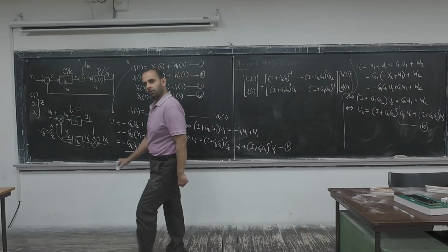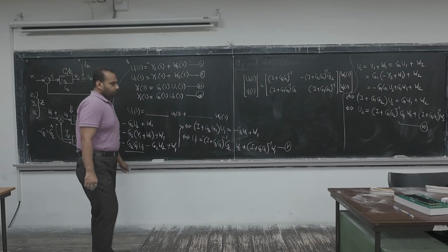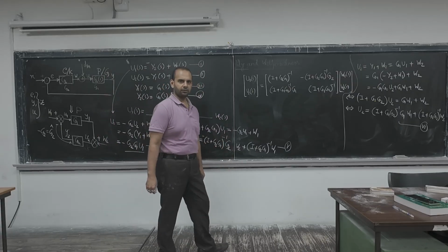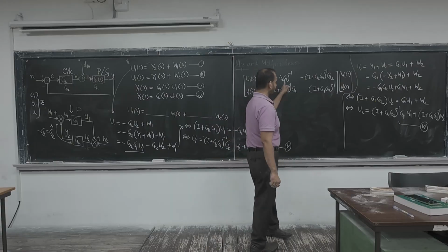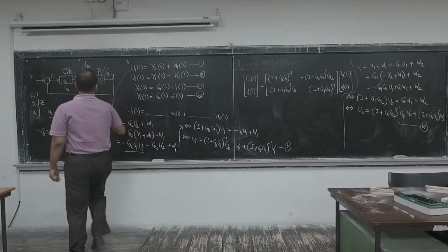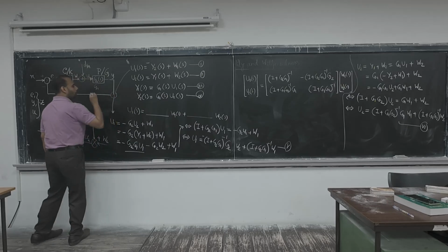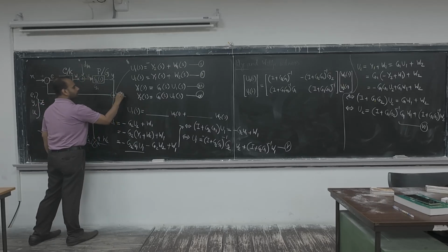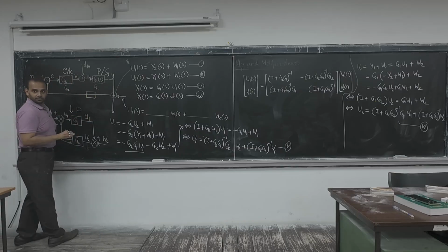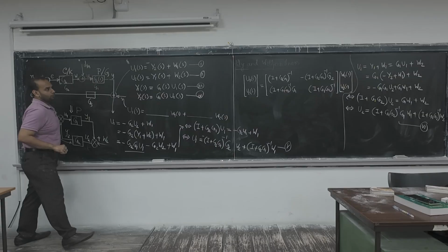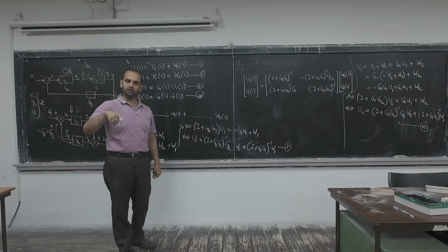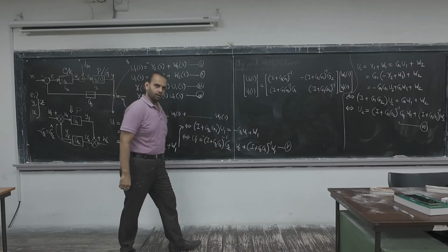Is it fine? So in this way, even if you have another component, then it would be 3 cross 2 transfer function matrices, but always you will find this I plus G2, G1. Or suppose there is a noise, eta, and here you have a sensor transfer function, G3. Then what would that be? I plus G1, G2, G3, or G3, G2, G1. Okay?